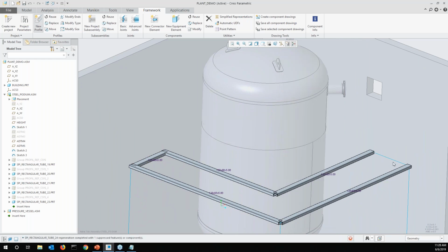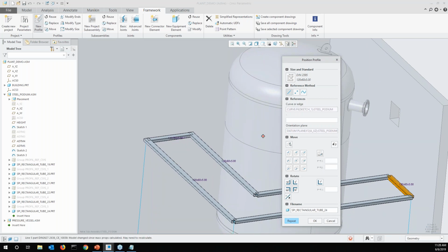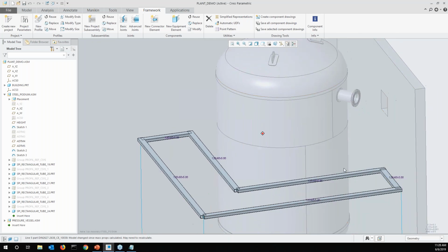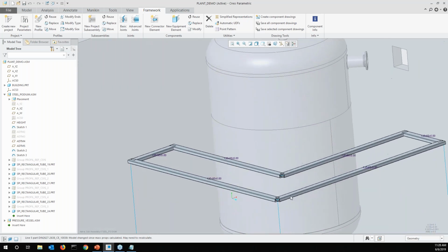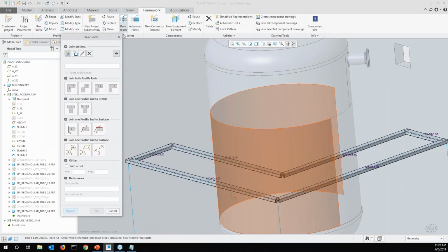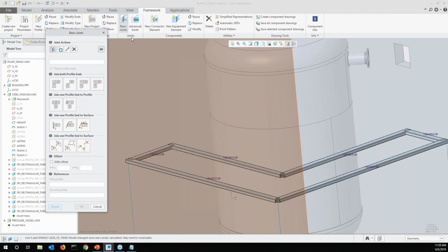Okay. So do the same thing here on this end. I'll rotate this, and then I want to have the edge of that beam align with the edge of that curve, and I'm done with the placement of this top sketch. So after you've placed it here, you can define your joints, and you have different options for joints. You have the basic category where you have the most common profile ends, and then you can get a little bit more advanced, as I'll show later on, when you have different types of cuts and profile ends that you have to work with.